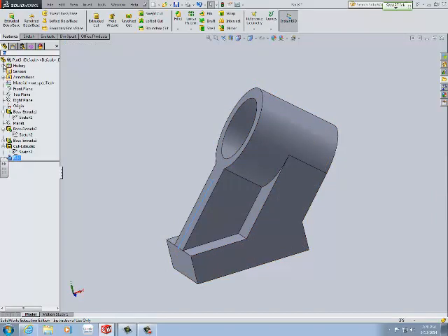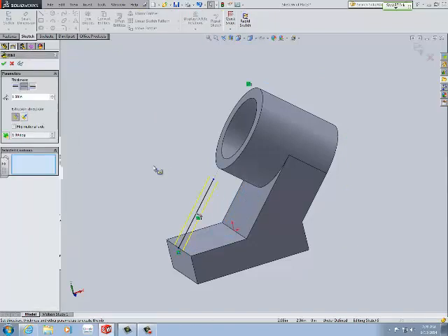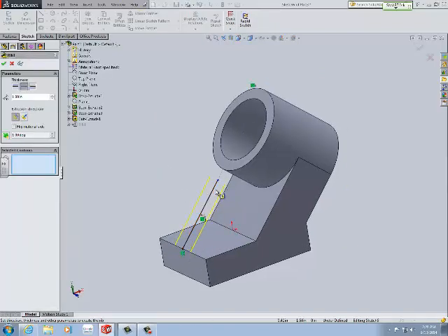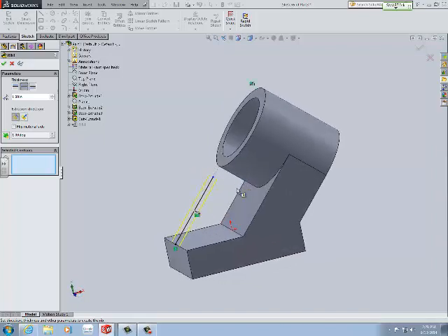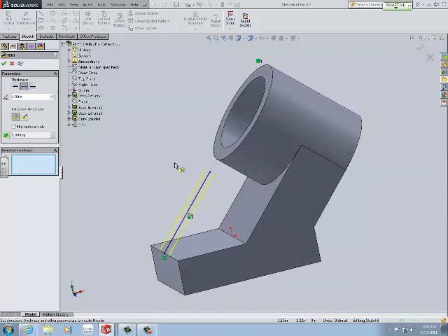That creates the rib just like that. So you already know what the mass was before the fillets, and now you see the drawing. I'm going to have to go back at that point to the line at 48 degrees. For the rib, all you really need to know is the width and what direction it's going. There are two different options. You can pick one direction or the other direction, but we're leaving it from the mid plane. The program is smart enough to make its own decision. Now you probably won't be able to see it on the drawing, but it's going to go up to the surface until it collides with it, pretty much, so it automatically does something like this.